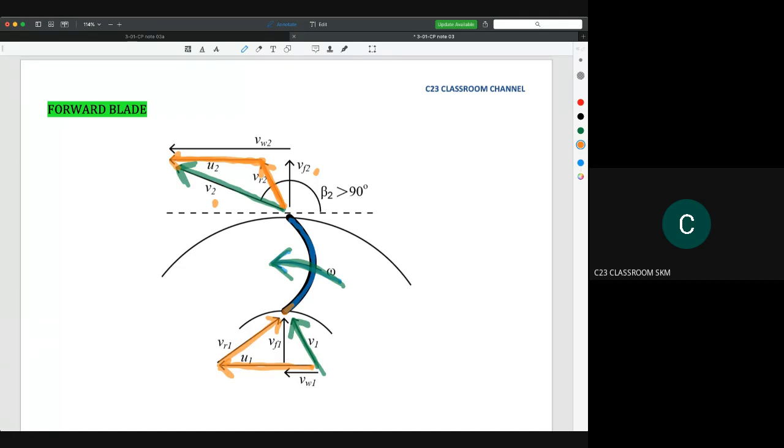Another thing, please bear in mind that the velocity vector is a closed loop, with the resultant velocity. This means that if the resultant velocity starts from here to here, the component velocities need to start from here to here, and then continue from here to the end point here. Now you draw the first component velocity. Next, we draw another component, which is related to the ideal condition.